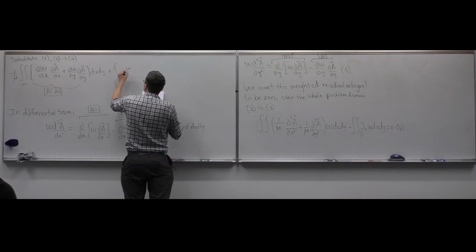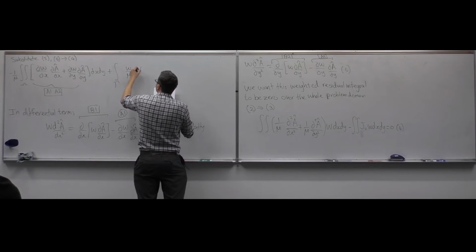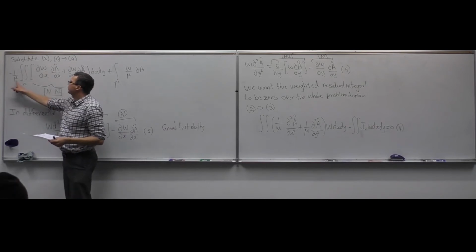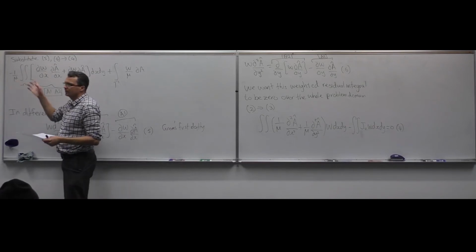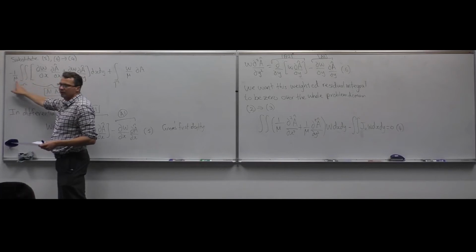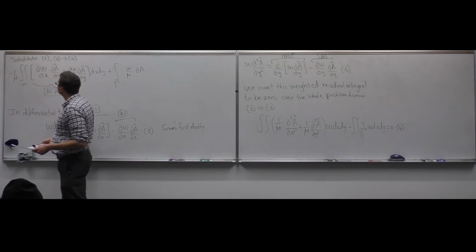So we have w over mu times del. Now, I was a little bit naughty here, but this is a simple example, and I took this 1 over the permeability outside of the integral. That would mean that the value doesn't change inside of that area.